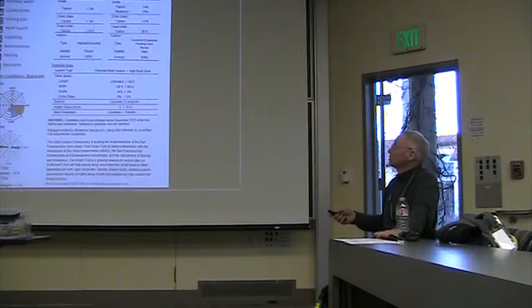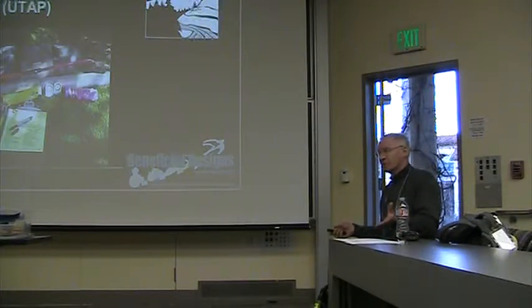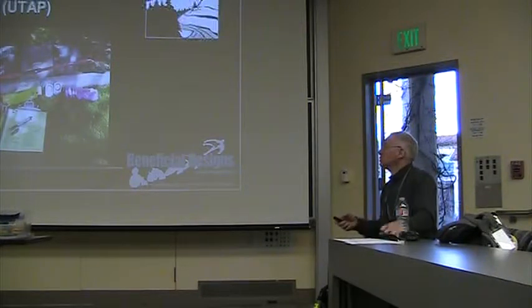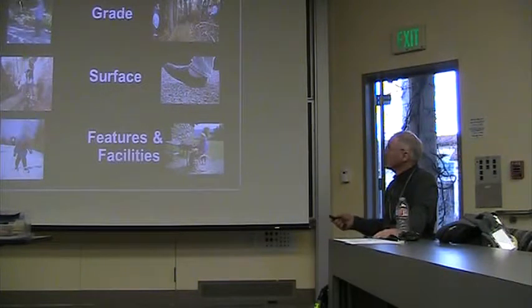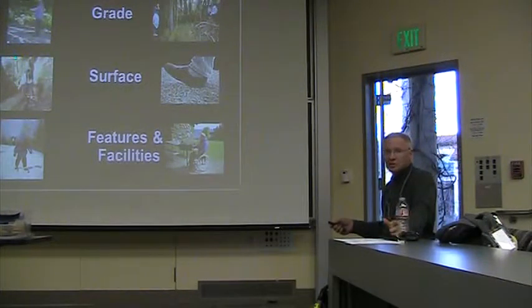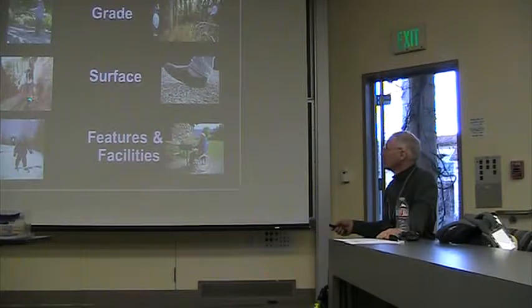And the Coastal Conservancy with the state of California is going to use this system for all their water site landings. For trails, we have a different process called the Universal Trail Assessment Process. And we use some simple tools: a roll-a-wheel, a smart level that shows us the grade, a compass, a clinometer, and measuring flags. We go out on the trail and systematically measure our distance down the trail. We measure the grade using a clinometer to shoot the typical grade. We get the tread width on the trail, very narrow tread width there between those rocks.